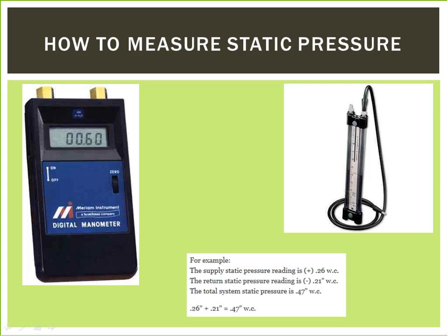Drill test holes using a 3/8 inch drill bit with a metal piercing tip. A bullet tip drill makes a clean round hole. Make sure to use your drill bit sheath to prevent from drilling into the coil. If there's duct liner inside, be sure to penetrate it to assure a good reading.